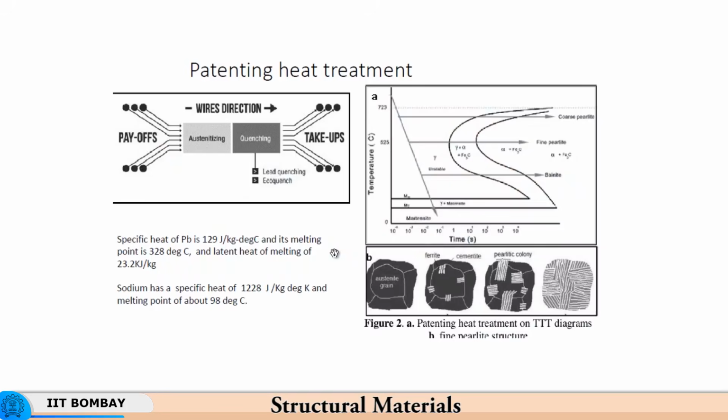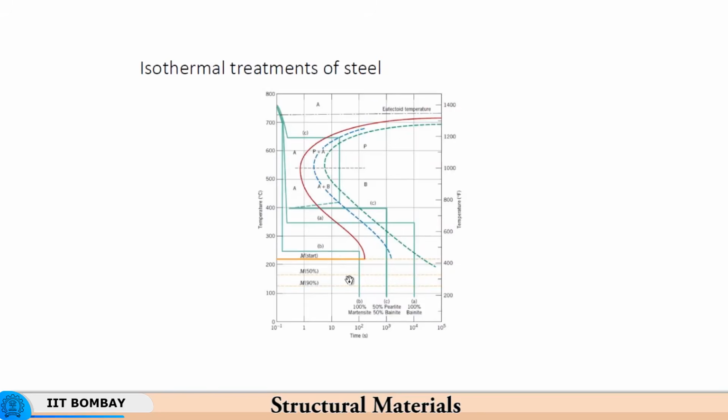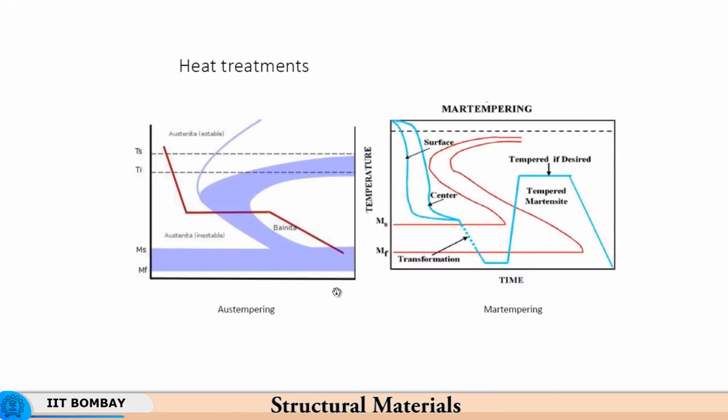So earlier what was shown here is cooling very rapidly. So here very rapid cooling was shown, but it is not enough just to cool it rapidly, just get bainite and be done with it. The stresses which are generated during transformation have to be relieved, and so there is some tempering of bainite taking place in the austempering process. So this is one process where the hardness is high and the strength is also very high.